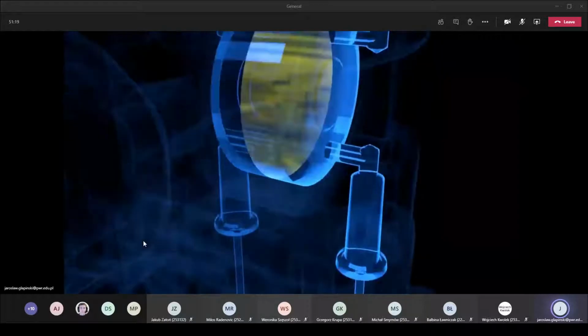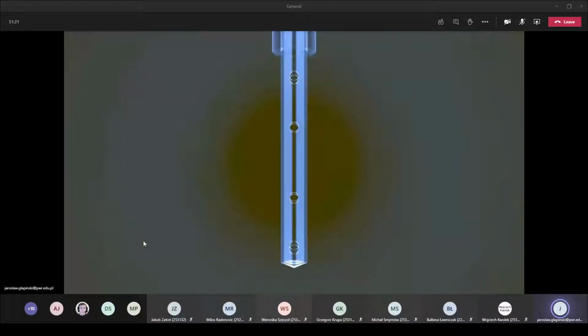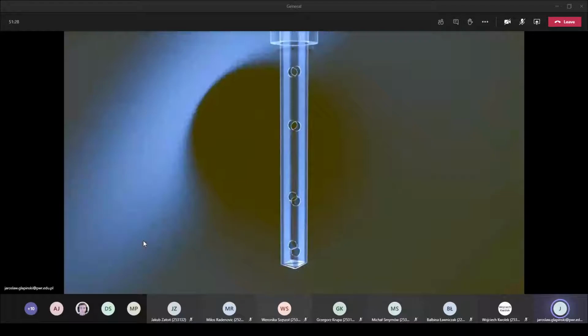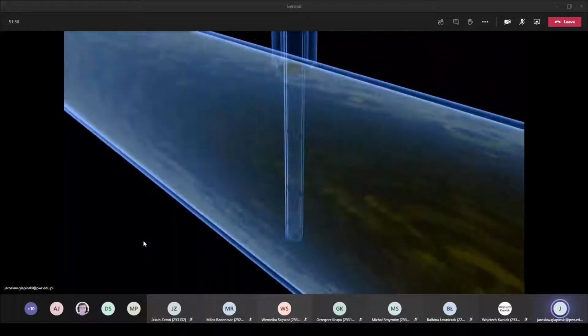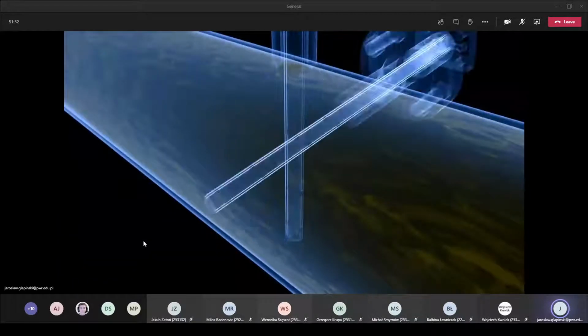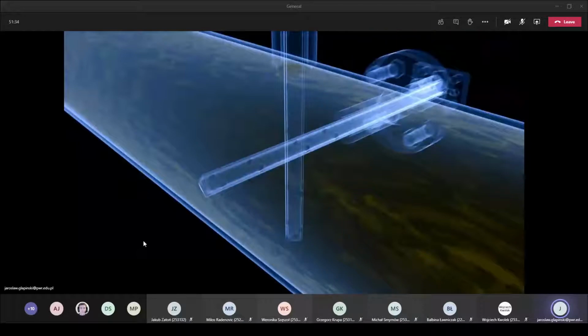The individual pressure taps are distributed along the entire pipe cross-section to ensure a representative measurement. If there is strong interference in the flow profiles, it's advisable to fit a second pitot tube, rotated by 90 degrees.